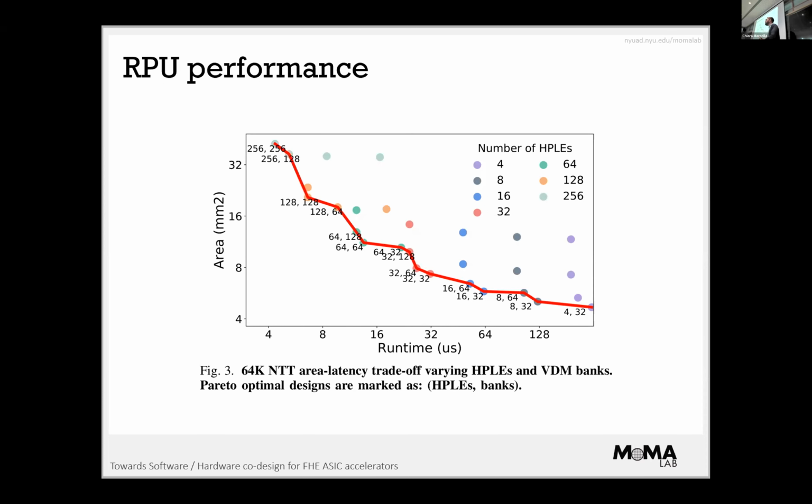All the papers, F1 and the others, they all do 32 bits because I think they're more used to 32-bit data types. And indeed, the multipliers can be more efficient when they're small. Still, RNS gives you problems at a higher level, including key switching. So there's a balance to be found on how much RNS should be added for what you lose by the inefficiency. There's an efficiency of the multiplier as you increase the bit size, but the key switching matrix increases and you need more data movement. So there's some sweet spot to be found. I cannot give you a solid answer yet, hopefully in a few months.